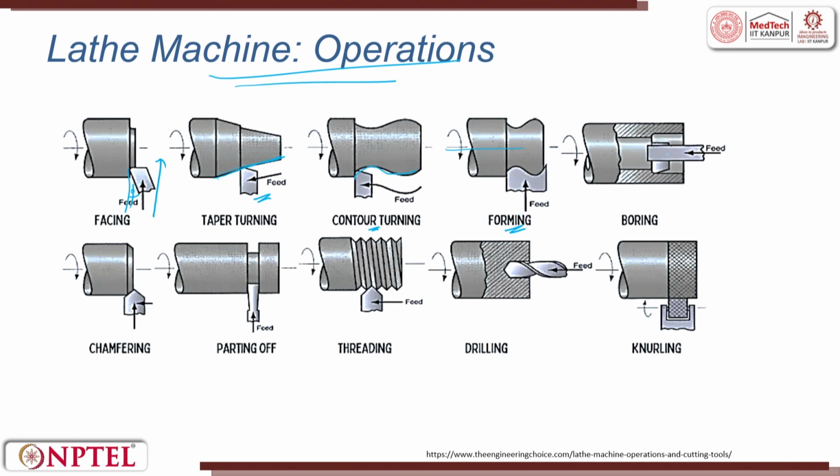If you want to bore a hole, that means making a hole in the shaft, we call it a boring operation. If you take an analogy, there are a lot of tunnels to be made for metros as well as for bridges. They try to bore. In a bore, the tool is attached to the tailstock and the feed is given to the tailstock.